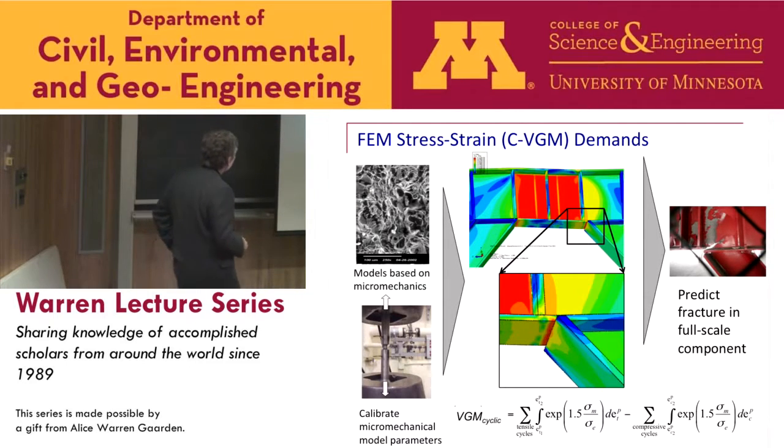Now, one of the things that was a subject of debate, I'm not sure if it was litigation or just debate, was that this structure was not built exactly the way it was designed. It was designed where these brace elements here would have a stiffener plate and they'd align right at that point. Well, on this side, they were a little bit off. You can see the brace comes in a little bit off from the stiffener. And so you would say, well, that's going to concentrate strains there. But there's still the question, how much does it concentrate the strains to drive the failure? Like, how much worse is this side than this side over here?